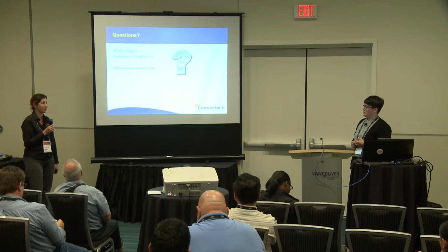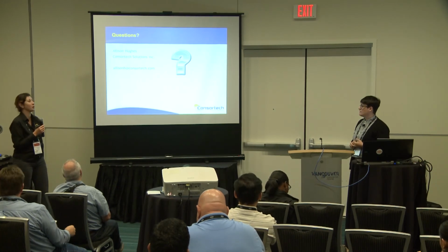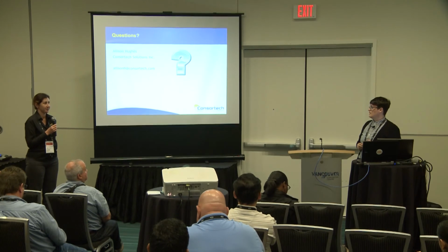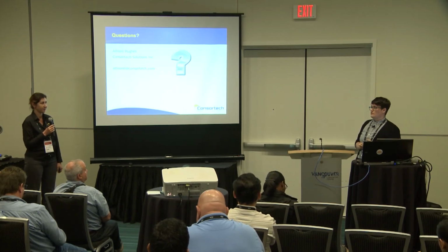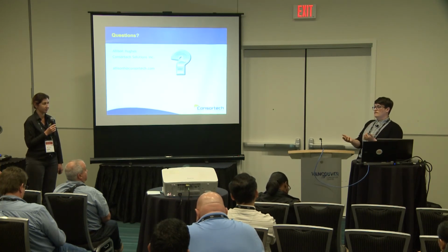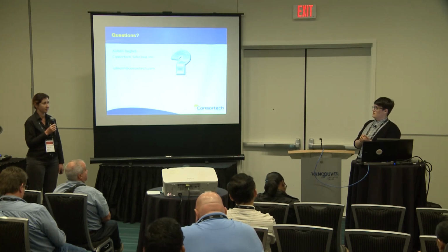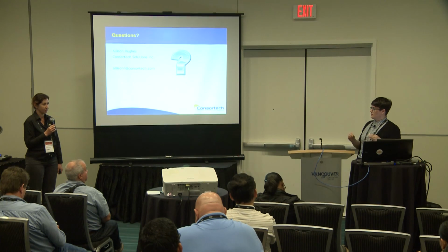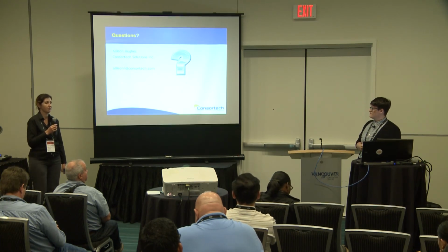Oh, that was even one to many rather than one to one? Yeah, exactly. Oh, okay. Yeah, I see. That's exactly why, to allow one to many. And we call that a soft split in the line. So if you split the line, but you don't actually create another attribute record, it's called a soft split. So both pieces of that line are associated with the one attribute. Oh, okay. Yeah, I see.